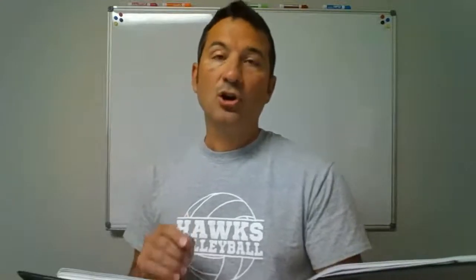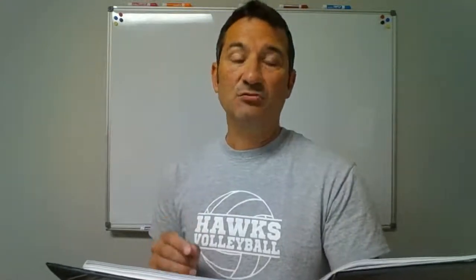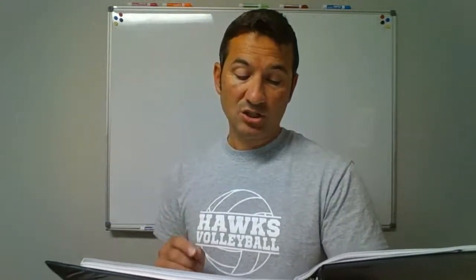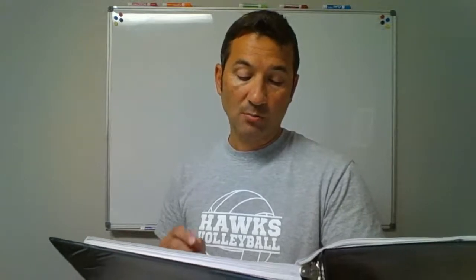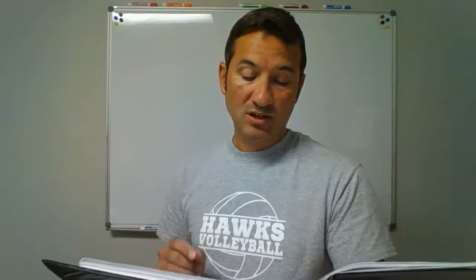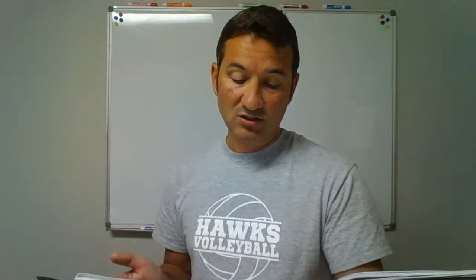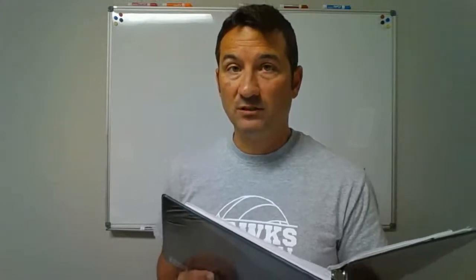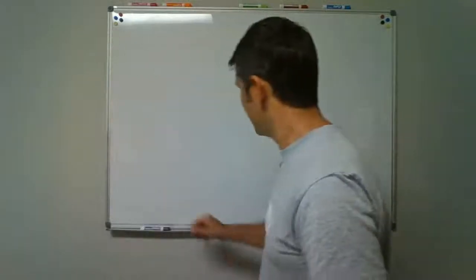It says where the code provision is less restrictive than the conditions of the listing, the equipment or appliance, or the manufacturer's installation instructions, the conditions of the listing and manufacturer's installation instructions shall apply. So basically what you're going to do is go with the most restrictive. Okay, the most restrictive.